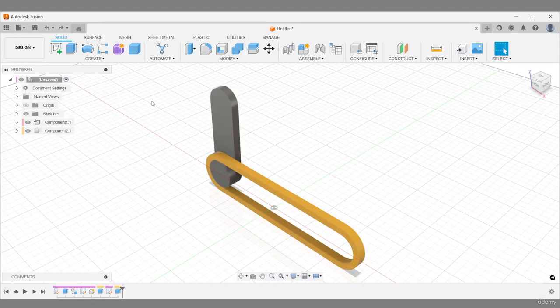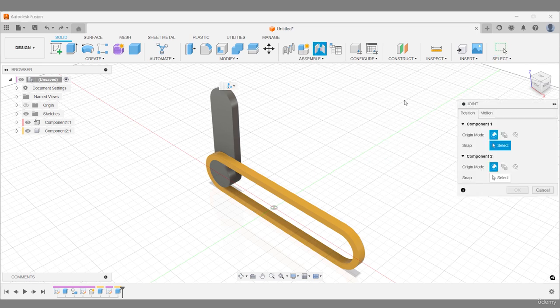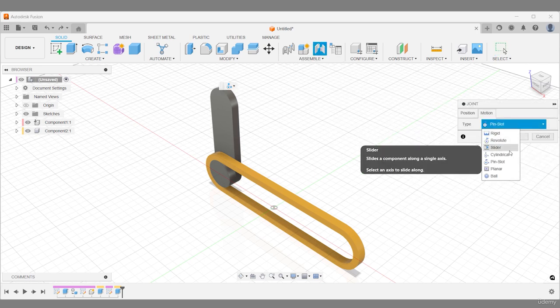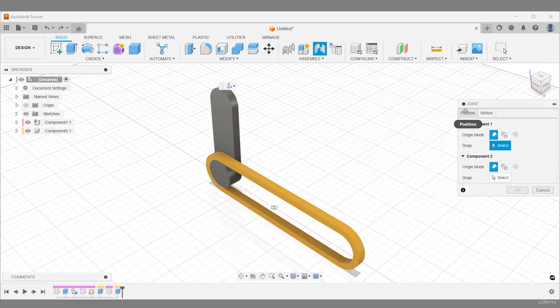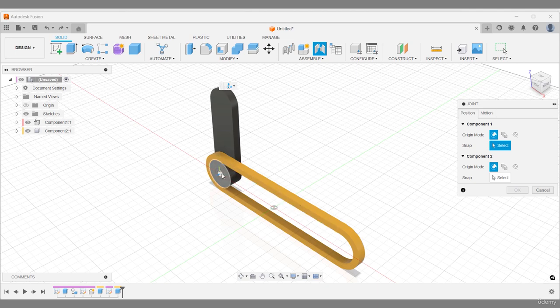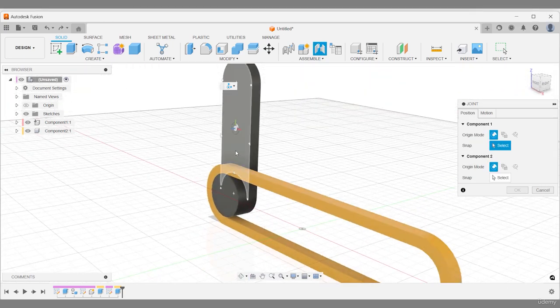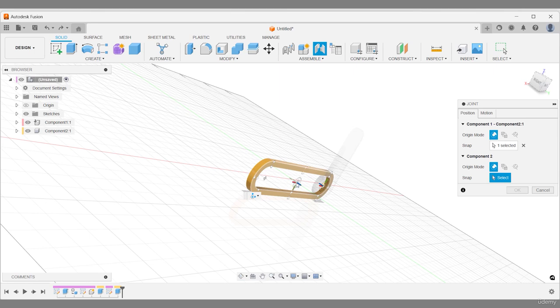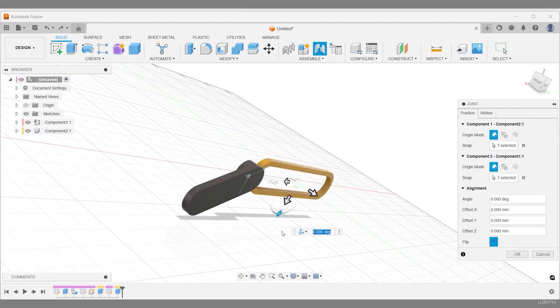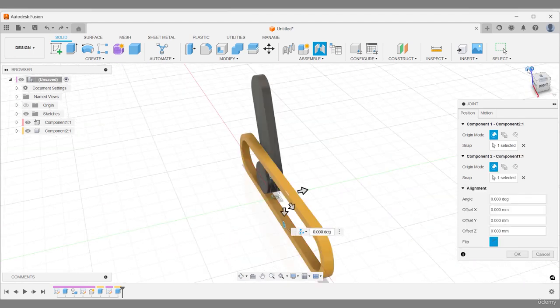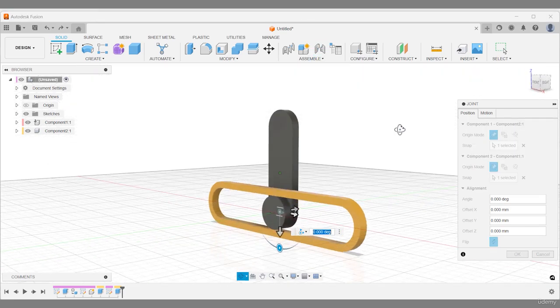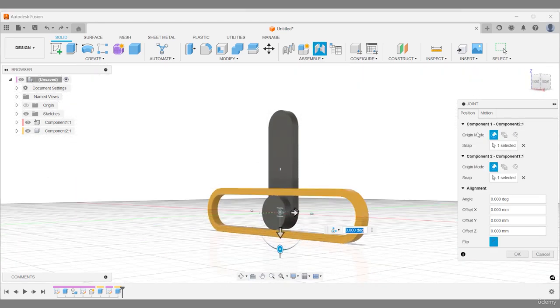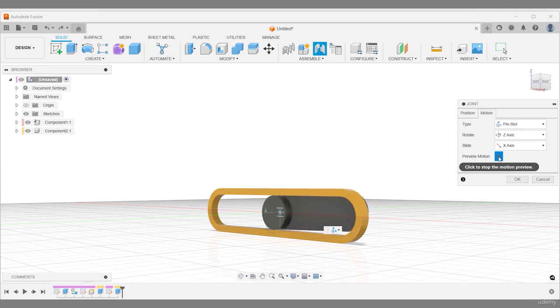The pin slot joint rotates and slides your component on two different axes. Finding your snap point can be tricky. You can make it easier if you lock onto a plane. Hover over the face, press and hold Control on your PC and find your spot. As you see, this joint slides along one axis and rotates around another axis. You recognize the possibility to preview motion for one or both motion limits.